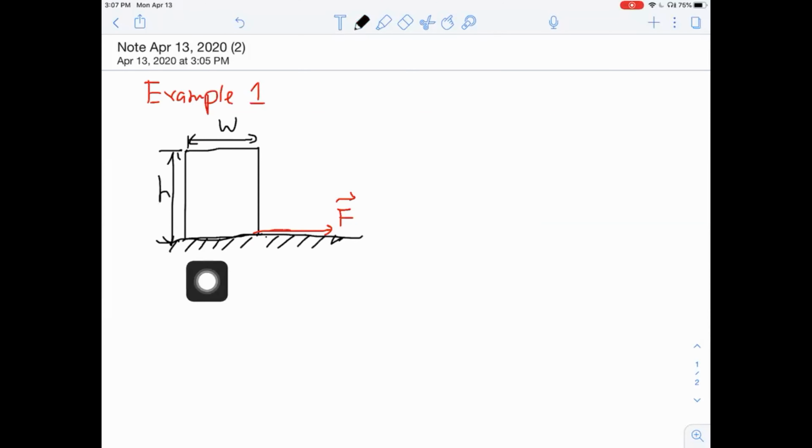In the problem statement, they will give you the dimensions of the rigid body, which in other words tells you the location matters. So when you draw your free body diagram, where you put forces on the rigid body free body diagram could have a big impact on your result. So let's write out all the given information.